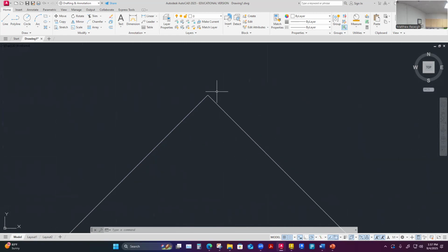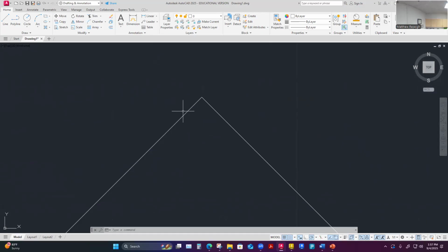If I zoom into this point, what I really need is a distance from here to here and here to here, where I'd want to chop that off, kind of a triangular chop off here. So I can input that measurement. And a lot of times when chamfers are on our drawings and on our parts, there is usually a dimension associated with the chamfer. It's common in machining to break an edge and add a chamfer on a lot of different machining parts. Just like a round is really common, also a chamfer is really common.